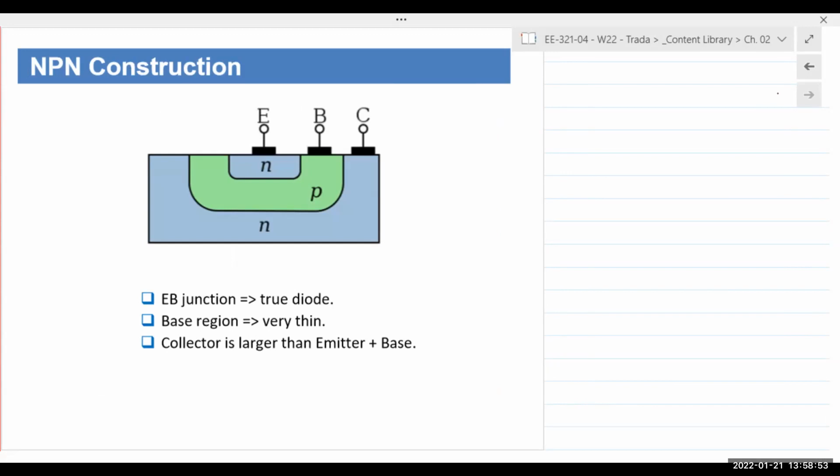So the way diodes are made is basically you have a silicon wafer, let's say a P-type material. Then you open up a small opening from the top, and you insert N-type material from the top. When you insert N-type material, what do you have inside the wafer? You have N and you have P. You got a PN junction.